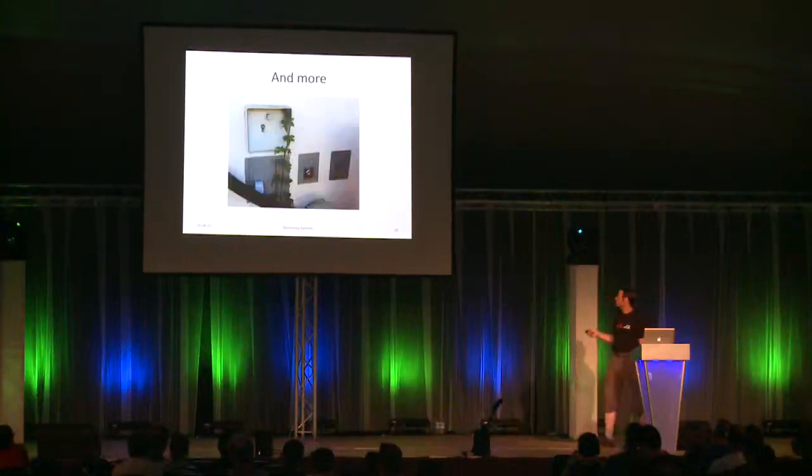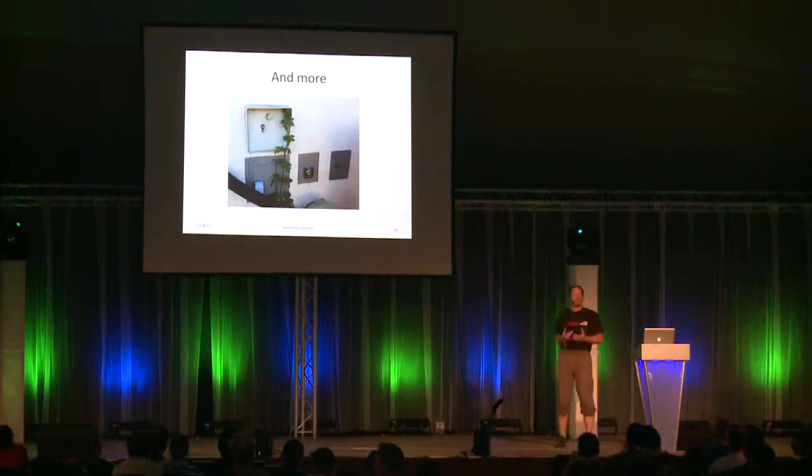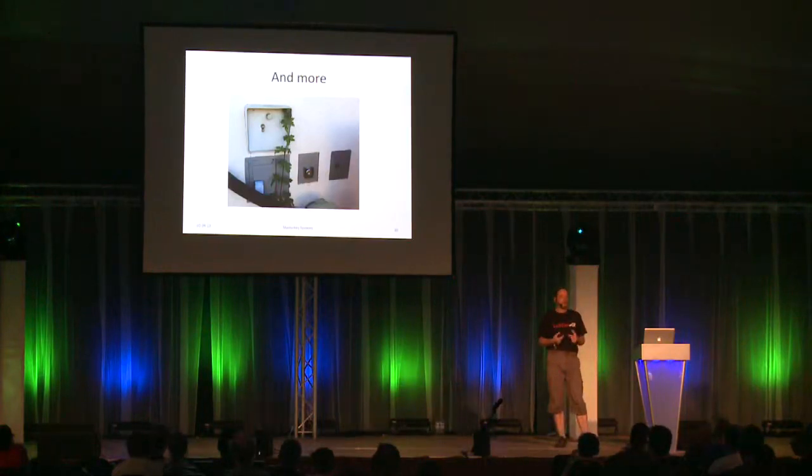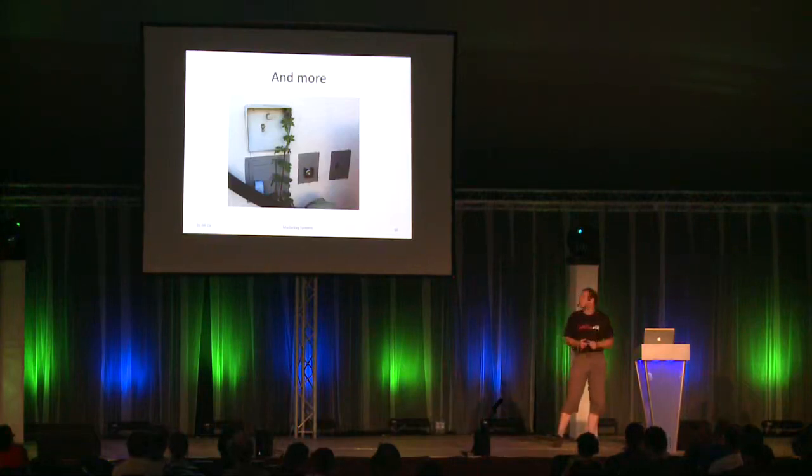This is the protected version. That's only the normal version. The protected version has two hatches on it, and we have a fire alarm system. Only when the fire alarm system is engaged, so some fire alarm inside the building, can I open the first hatch. Then I need the key to open the second hatch, and this will also be monitored and alarmed if opened without authorization.